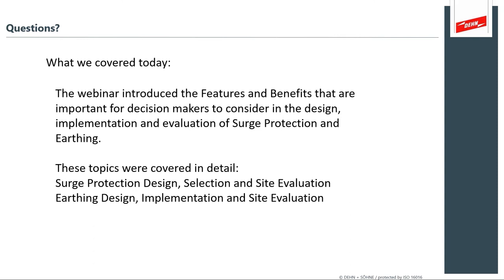With a long wire, you're essentially sacrificing the effectiveness of the surge protector. A long wire with small gauge and lots of bends is not as effective to control the voltage. So that's the idea behind a short wire, heavy gauge, and you'll see that in the installation instructions for most surge protection devices. They really do want you to put it as close as possible to the victim so that it's most effective in controlling the voltage.